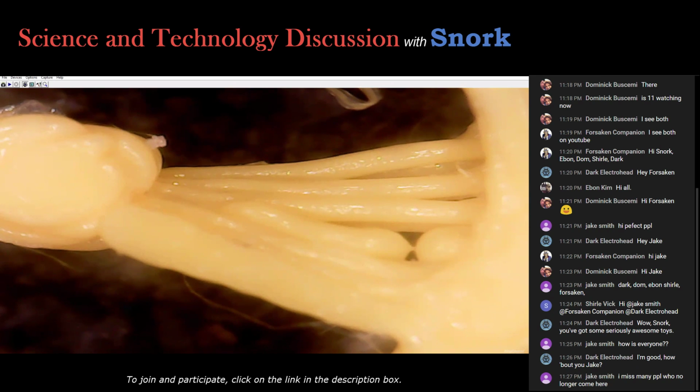But in the case of this, where it had materials that are suspended in air, sometimes two materials are 3D printed at the same time, and then one is eroded away. You can use a water soluble or an alcohol soluble plastic, and it dissolves away, and you have a much better surface than the one I created here, and a lot less warping.